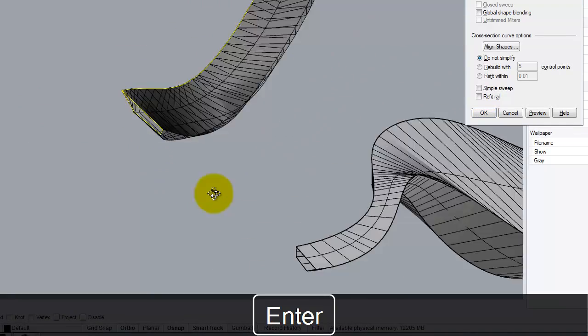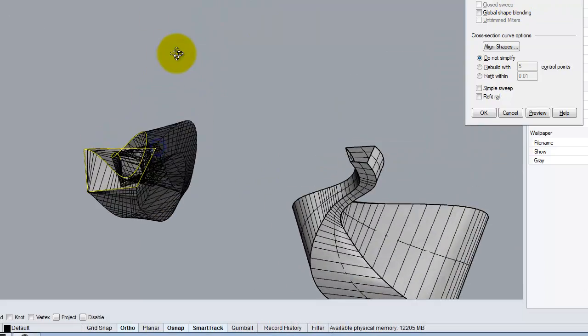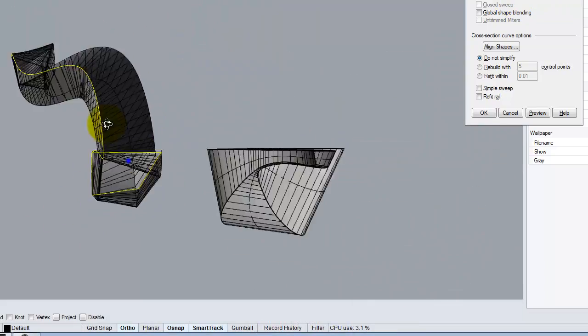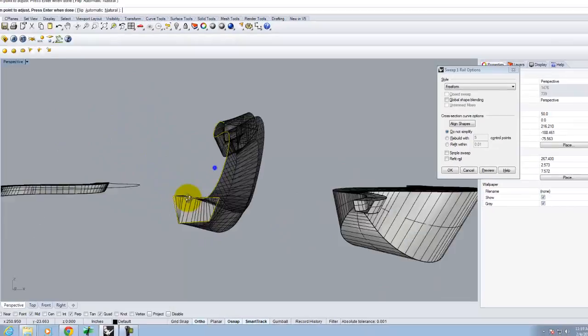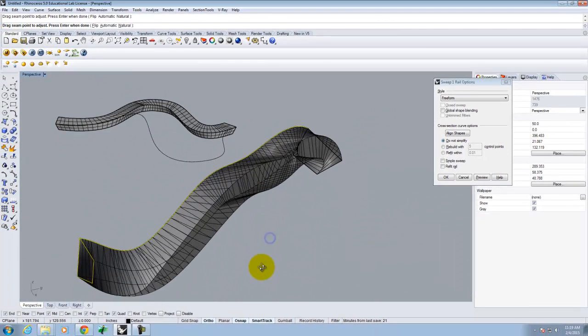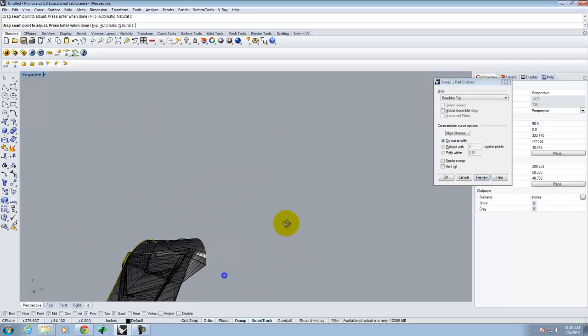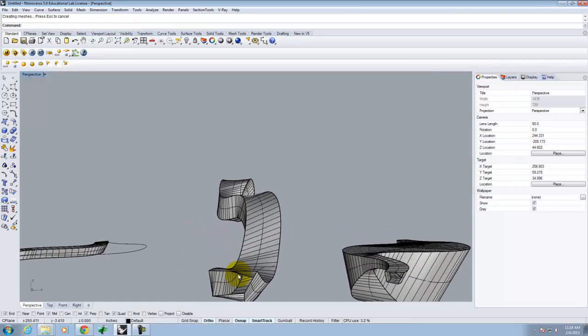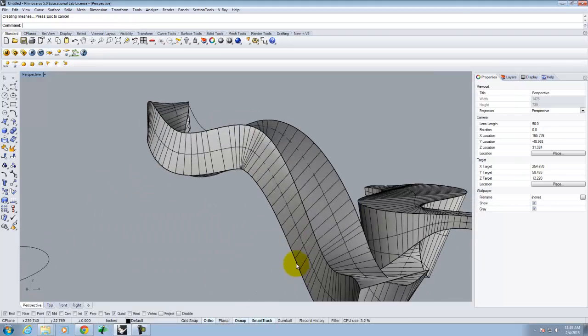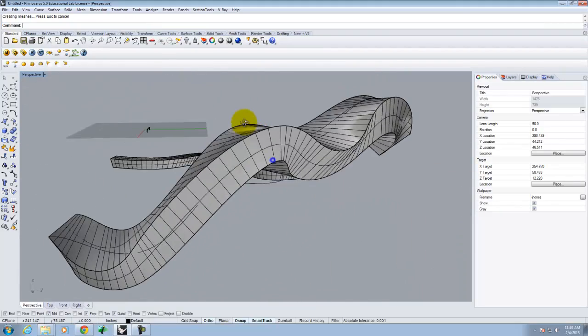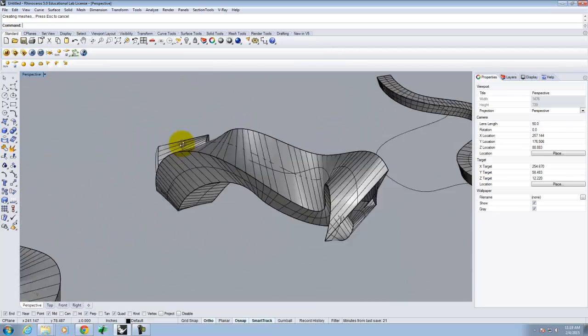Now, in this context, right, it's freeform, so it tips down there and then kind of tips up and over as it goes along. You guys kind of see how that falls? If I switch from freeform to road-like top and then click preview, it should stay flat as it goes along. See how it's flat as we go through? So it's a different structure to it.